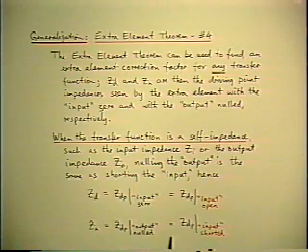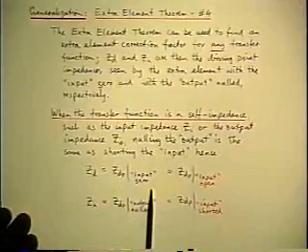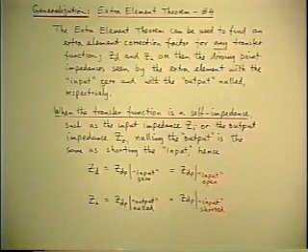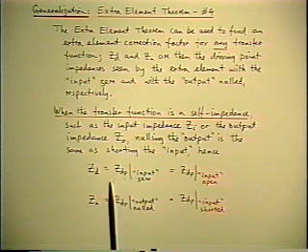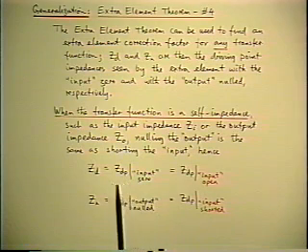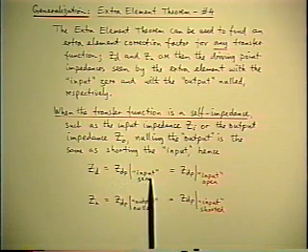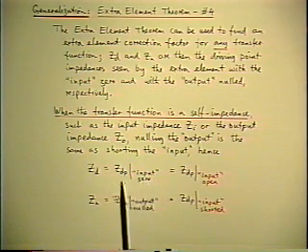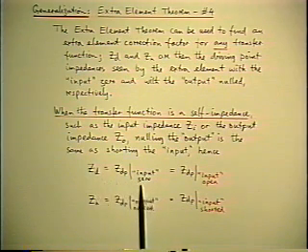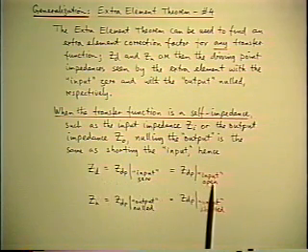And there is a special case of that when the transfer function is a self-impedance, in which you can shortcut the conditions for the calculation of the two driving point impedances. ZD basically is a single injection calculation when the input is 0, which, in the case of a self-impedance, the input is a current, and so the equivalent condition is you calculate ZD when the input is open.